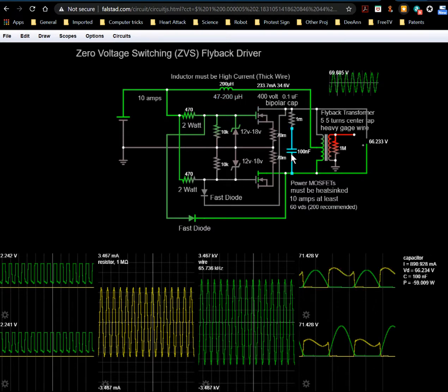So this basically is a tank oscillator. You can look at it as a tank oscillator that happens to be fed from the middle. But there are a few epiphanies that you need to have. One is, if you have current flowing, let's say this transistor is on, so that you have current coming from your positive, you can ignore this. This is just a choke. It's not important for the fundamental operation of the circuit as far as oscillation, so just ignore that.